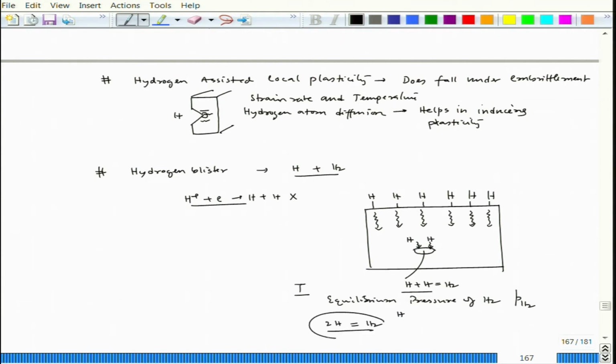Okay. So, this reaction would require, to reach equilibrium, a pressure that would be extremely high, several thousand, several hundreds of atmospheres. Because of that huge pressure created within this small volume, the void, the crack extends. So now it appears as a kind of fish mouth crack like this.